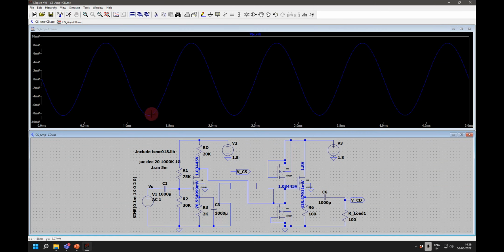Okay. So I am getting a good gain out here. This is what I am plotting. What is CD, output voltage only, right? It has not made any difference, right? So yes, sir. So you should try and do that in your circuits. Try to avoid unnecessary capacitors. If you are able to maintain the DC operating points close to each other, we can do that. Okay? Yes, sir. Okay.